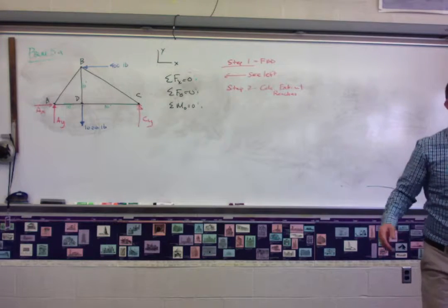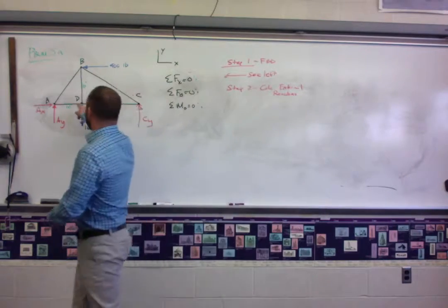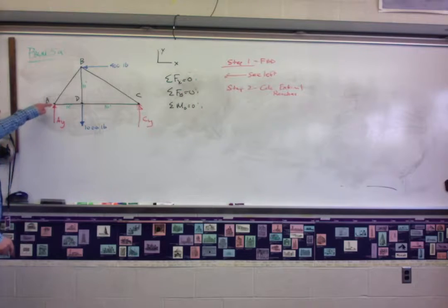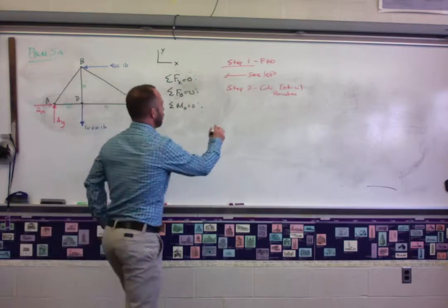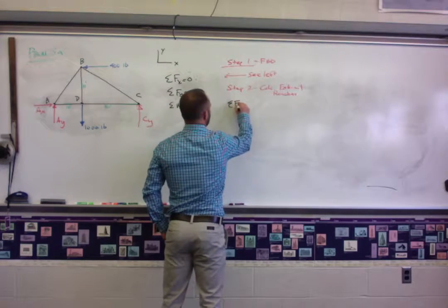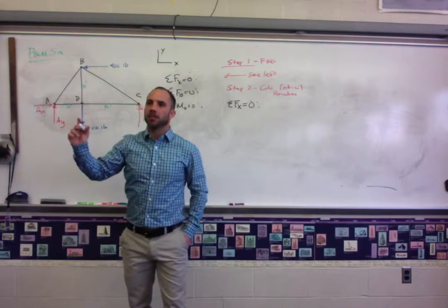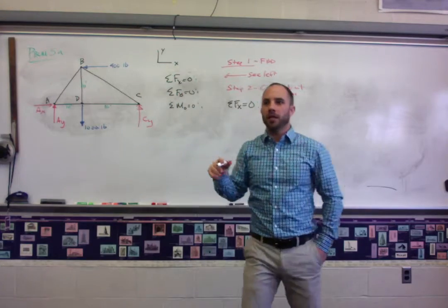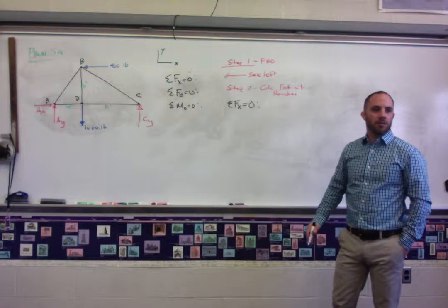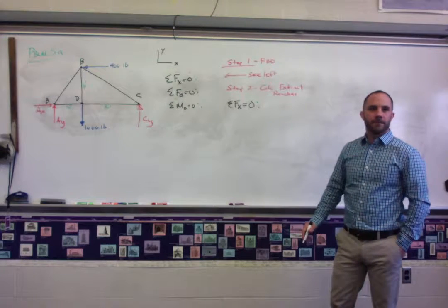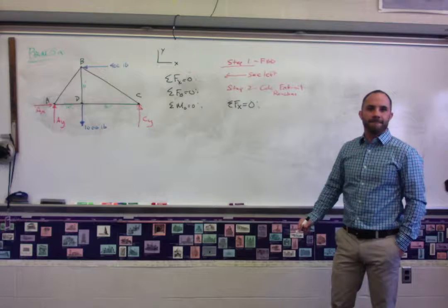External, internal, you're going to be able to calculate both of them eventually. So, first thing, in order to figure out the internals, we need to know what's acting on the outside. That's why we do that. All right, so first one: sum of the forces in the X. What forces are acting in the X direction? Only in the X direction. The 400-pound load and AX, right? Is he right? Yeah.